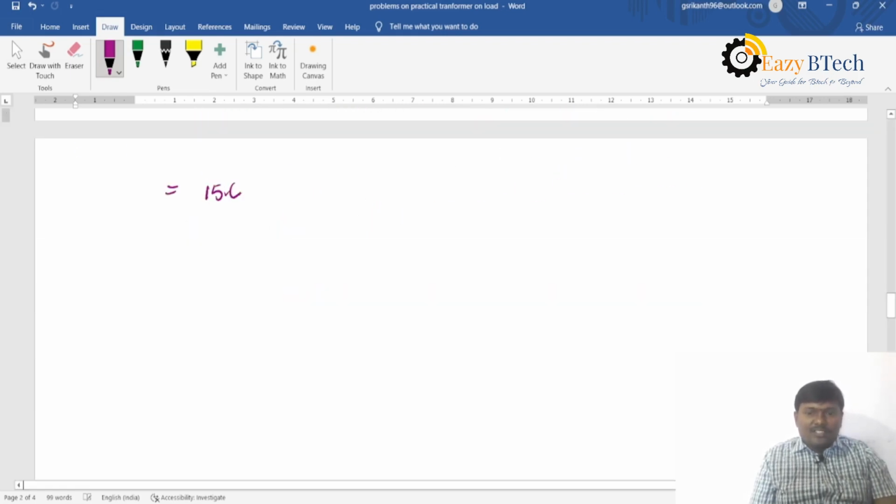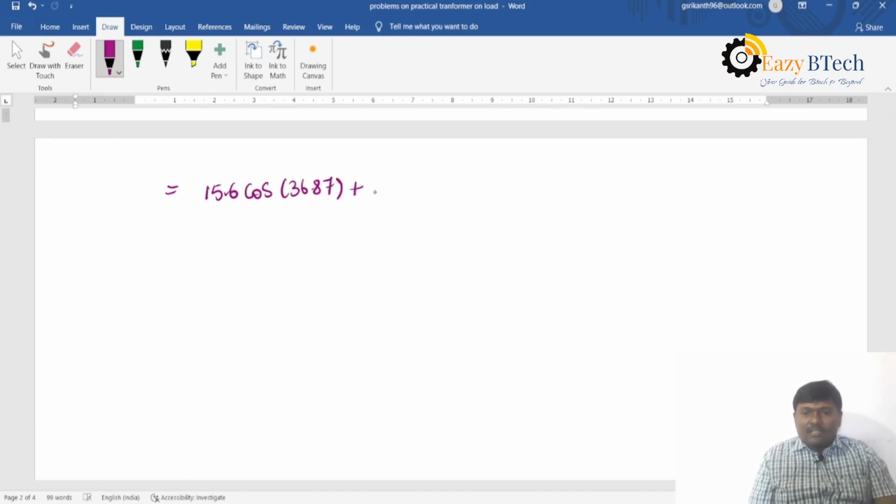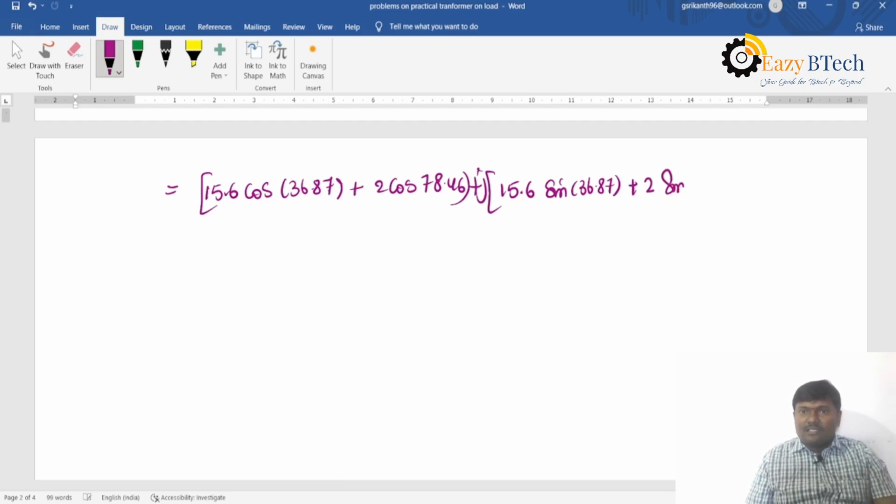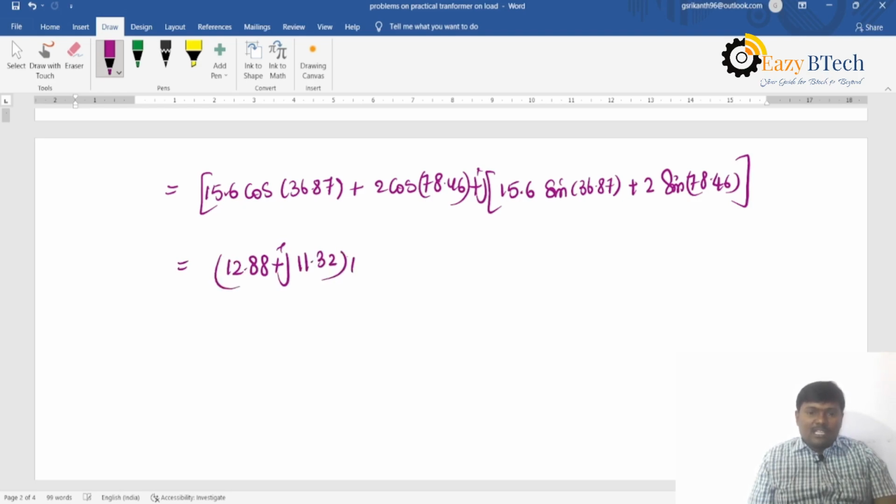Then 15.6 cos of 36.87 plus 2 cos of 78.46. Then 15.6 j times of 15.6 sin of 36.87 plus 2 times of sin of 78.46 degrees. So finally I get 12.88 plus j times 11.32 amperes.